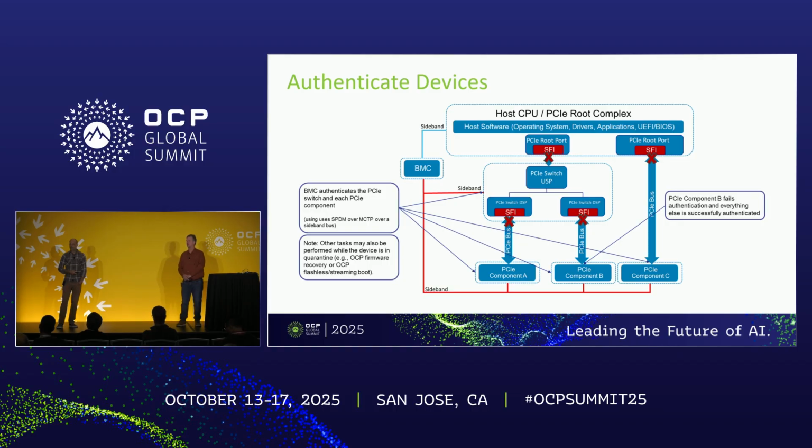Okay, so in this case, the BIOS and the BMC would have to have a mapping of the PCIe topology to the MCTP topology. Right, that's right. And there is some discoverability within PCIe MI. Not the topology piece, but at least enough identifying information to match it with your map. Okay, thank you.